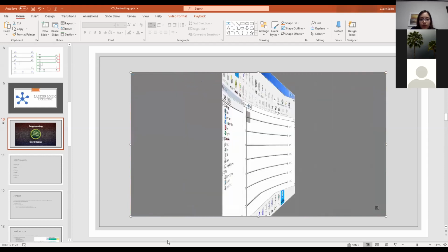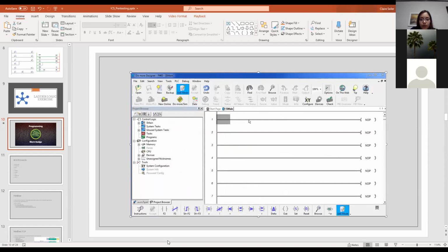Here we go. PLCs use something called ladder logic because it looks kind of like a ladder. Each line of code is called a rung, like a rung on a ladder. Think of this as the power, and we want to connect that power to drive an output like a light or a motor. In our case, it's the finish line lights. Now right now this power is running directly across this wire to the output.